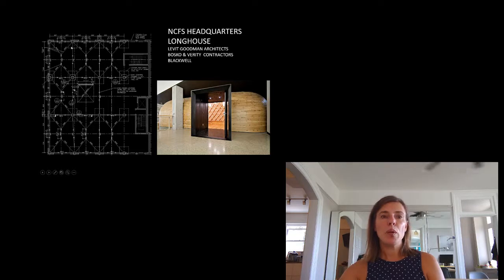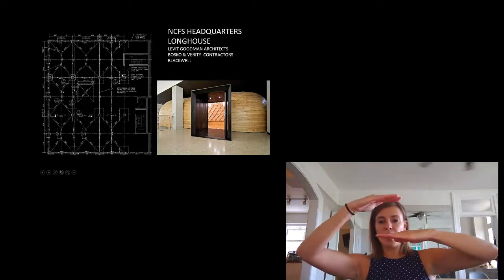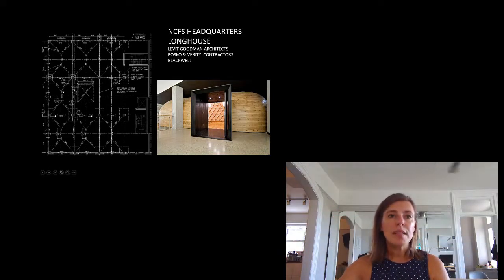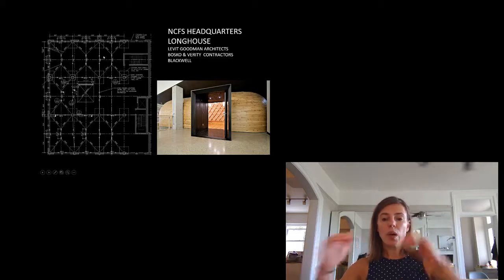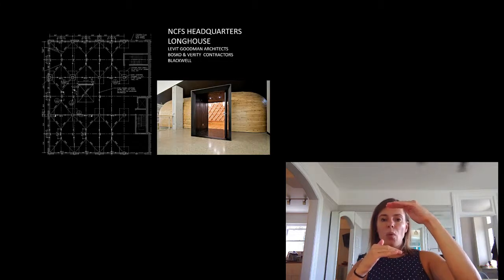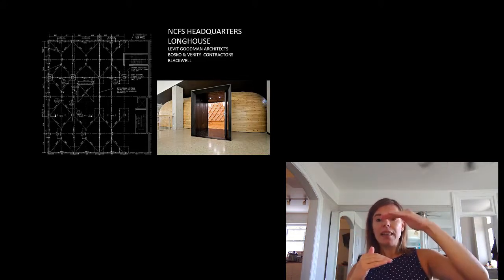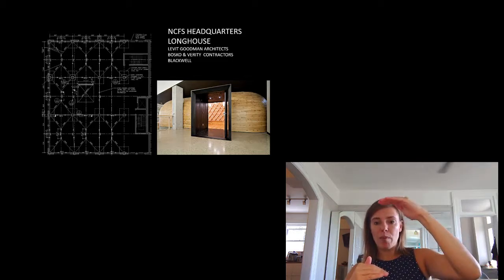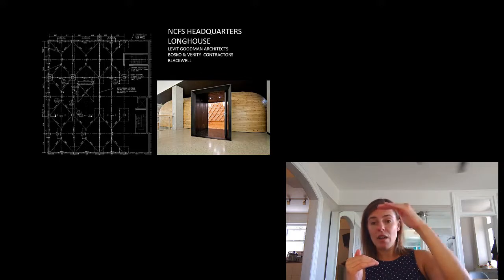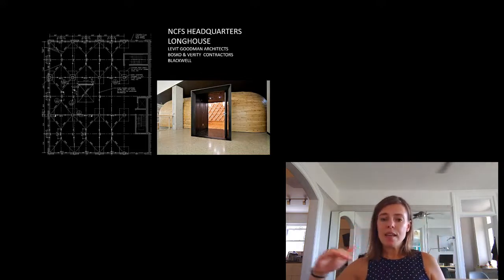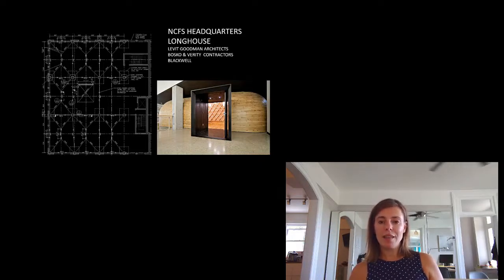So what we did is we put this filigree of steel members underneath the concrete structure, about this far underneath. And then periodically, where you can see these little dots right here, we put hydraulic jacks in between. And then we would jack up the hydraulic jacks that would push the steel down and lift the concrete up. So the steel was taking the load and unloading the concrete. And then the steel, we could tell how much load it had on it by how much it would deflect. So we were able to design the system, but also give them a calibration technique for that preloading in the roof. It was such a cool structure.